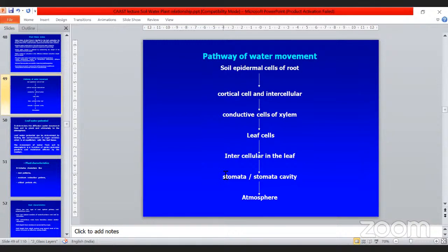Because compared to flood irrigation, if you give drip irrigation, it reduces water by 50%. And even from that 50%, if you go to partial root zone drying, it reduces another 20 to 30%. So naturally, we are reducing more than 70% of the water requirement of the crop. At the same time, we don't lose anything in yield, but the quality has been enhanced because of the stress condition. The tomatoes, the final product, have less water content, and this is useful for more pulp for the industry, so they require less energy to extract the water, and they get more pulp.